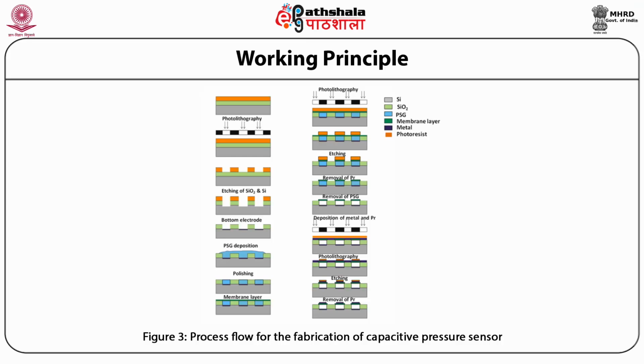silicon was taken, over which the photoresist was deposited using a spin coater. After that, a set of masks is used such that we get some part uncovered and some part covered with a photoresist. After this step, the etching of SiO2 has been carried out on the Si wafer such that the grooves become deeper on the areas where there is no photoresist.